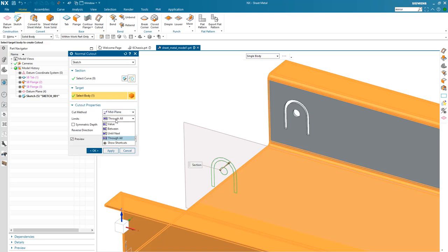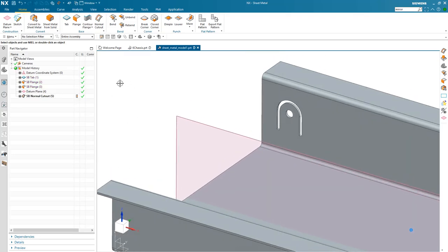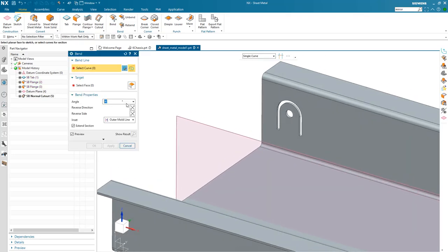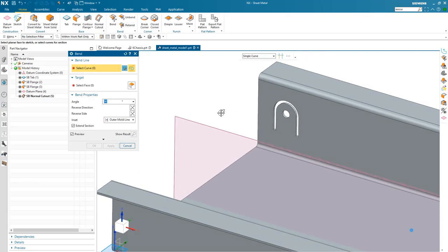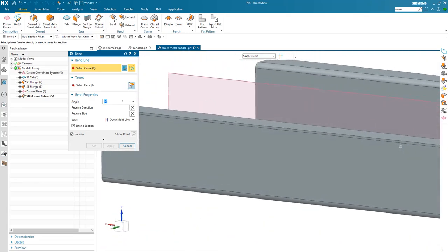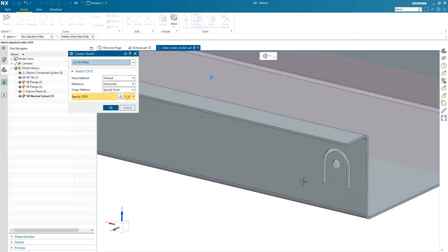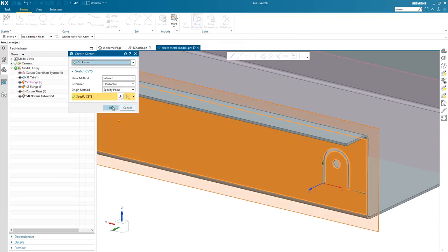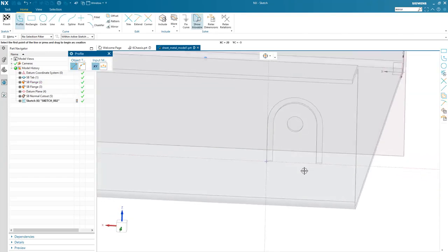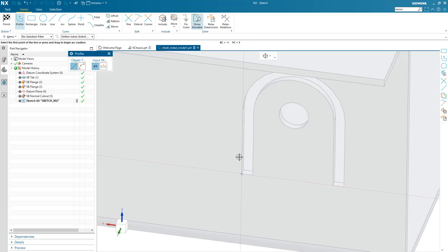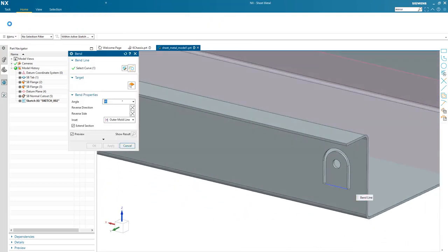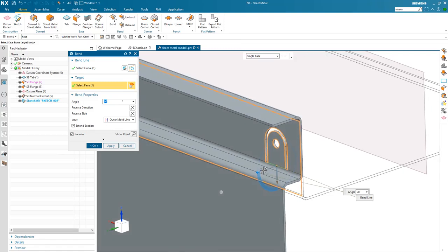That will give us the option to punch out the center part of that from the center to the outside on that particular flange. And then I just want to create a sheet metal bend. In this case, you can use outside, inside of the flange face, doesn't matter, so I'm going to go with the outside. It really doesn't need to be connecting. All I'm doing is just saying, where do I want this bend to make sense? So in this case, I just want that to be on the bottom of that. It doesn't need to be continuous or even touching the edge. Basically, that is just the bend where I want to take place.